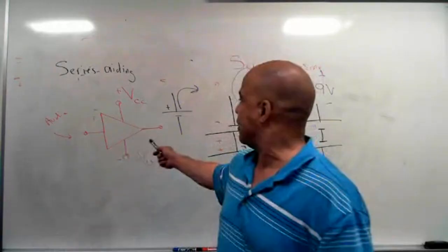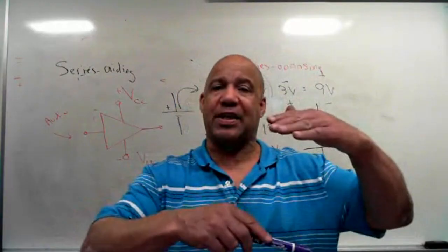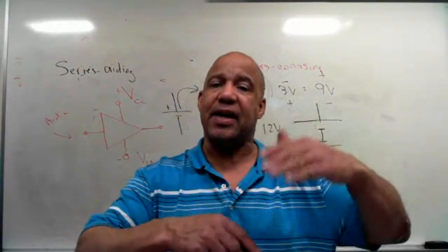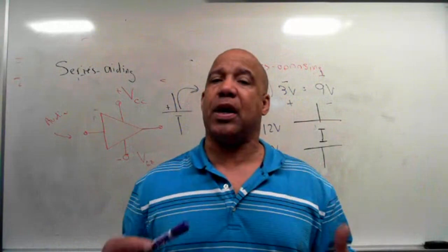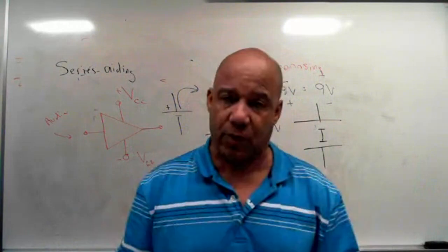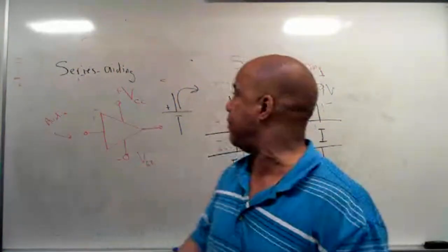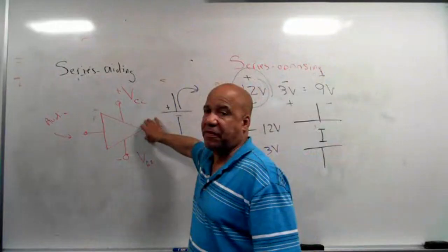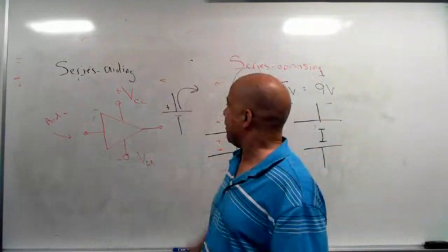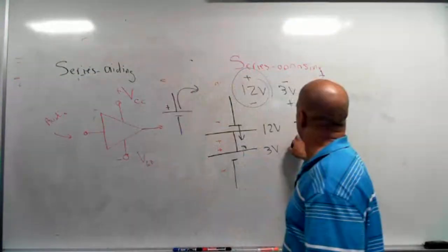Well, you can do this. If I have two 12-volt batteries in series, and they're series aiding, then I have 24 volts. So the point is that you put voltage sources in series when you want to increase voltage. Can you decrease voltage? Yep, you can do this. But other than that amplifier right here, which is called a differential amplifier, by the way, I've never seen it.